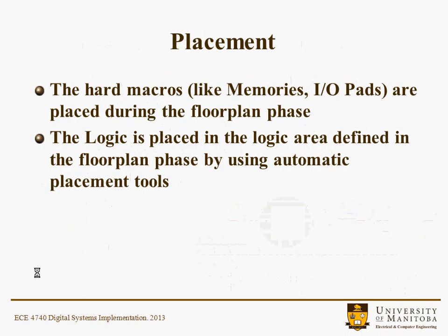Placement of hard macros, that's something that's basically pre-assembled. You really don't design it, but you want to use maybe memories and I/O pads. They're placed during the floor plan phase. The reason they're called hard macros is they're highly tuned pieces of silicon, and you don't want to reinvent the wheel. The logic is placed in the logic area, defined in the floor plan phase, by using automated placement tools.